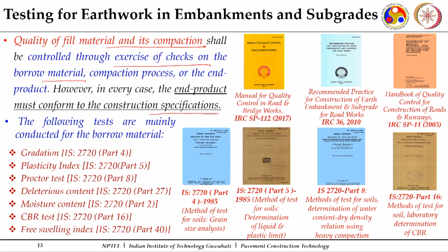So, the common tests which are done: gradation requirements are checked, plasticity index checks are there. We have discussed these tests. The Proctor test for determination of maximum dry density and the optimum moisture content is there, moisture content determination, strength in terms of the California bearing ratio, and free swelling test.